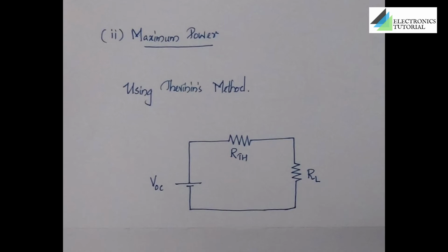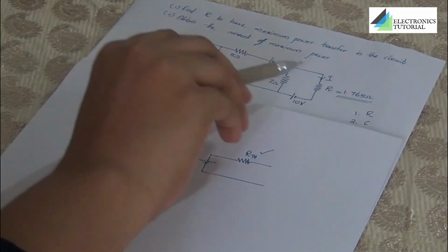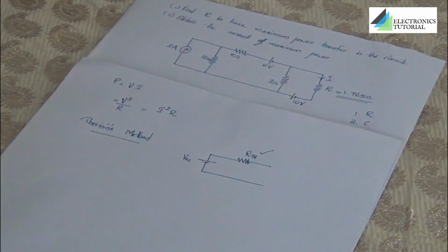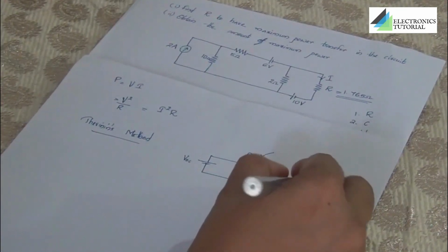The reason behind choosing this method is we have already got the value of RTH. As said earlier, RL and RTH are calculated in a similar manner. So we can write the value of RL in the position of RTH. One fact that should be highlighted here is that for a circuit satisfying the maximum power transfer condition, the RL and RTH values are the same.